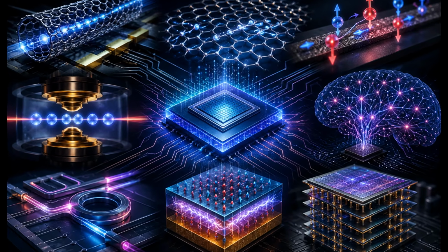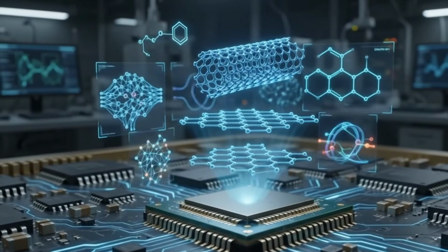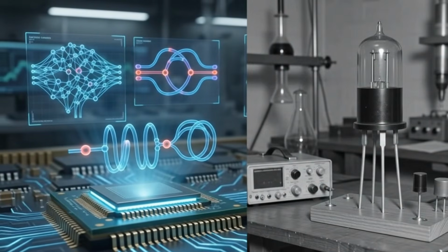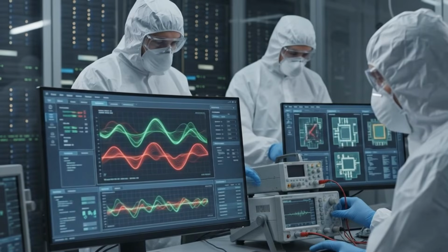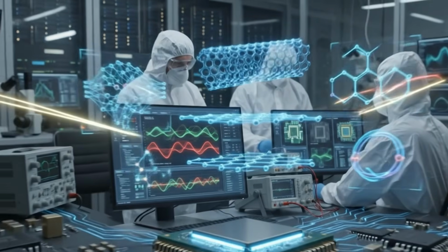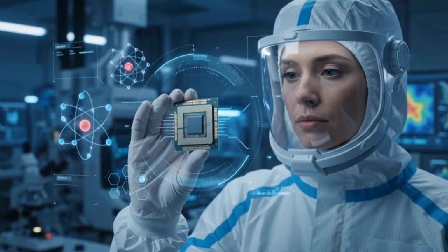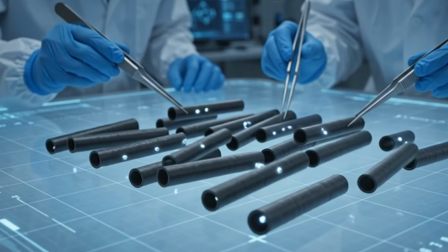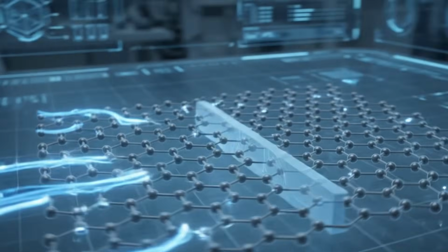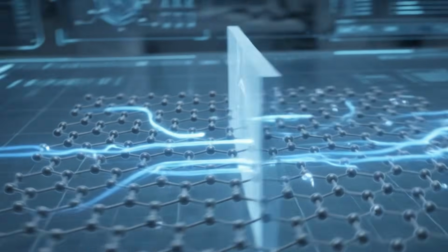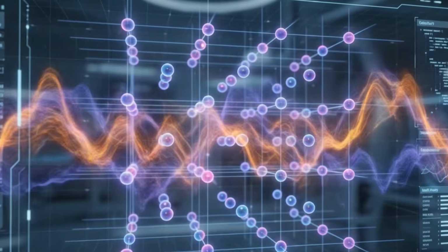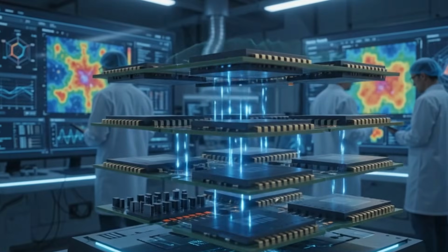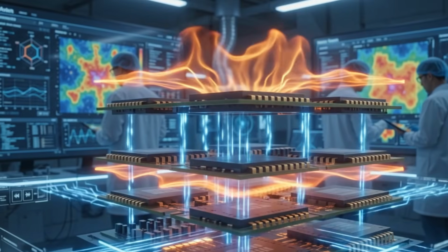Now, all of this sounds exciting, and a question might come up. If these ideas seem so powerful, why haven't they already taken over? Remember, even the transistors we use every day were once experimental ideas sitting in research labs. Every technology comes with its own challenges. CNTs face alignment and manufacturing difficulties. Graphene lacks a natural band gap, making switching difficult. Quantum systems suffer from noise and decoherence. Spintronic devices are difficult to fabricate reliably. 3D structures introduce heat removal challenges.